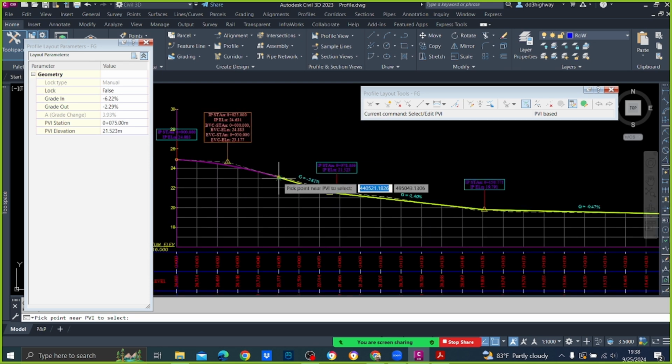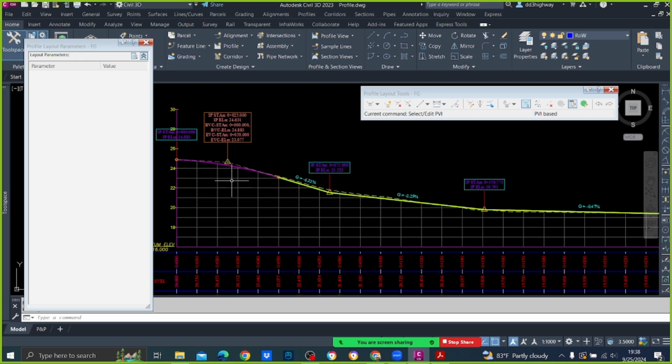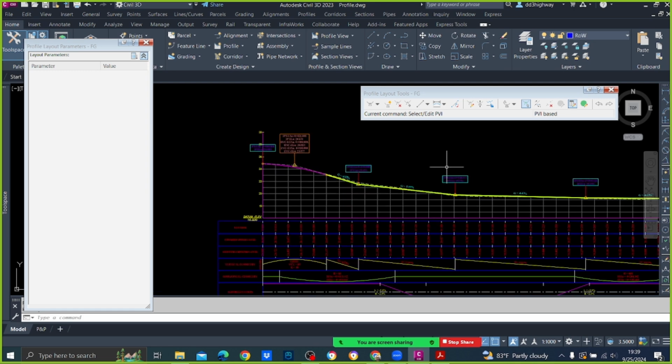So when it comes to here, it's 25, 25, that is 50, and you are having another 25 here. So the difference from here to here should be 50. Why? Half vertical curve length here, half vertical curve length here. Vertical curve length is 50 and you are having half vertical curve length here, that is 25, and half vertical curve length here, another 25, so that is 50 effectively. So 25 plus 50 is 75. Okay.